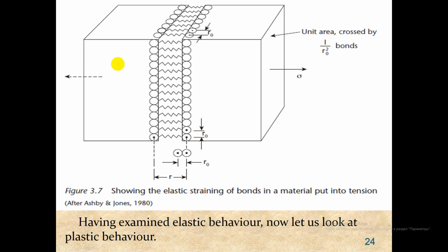If we release the tension, the piece of material will immediately spring back to its original length. This is elastic behavior. Elastic strains are temporary and are relaxed as soon as loading is removed. The same thing will be observed if we apply a compressive load.